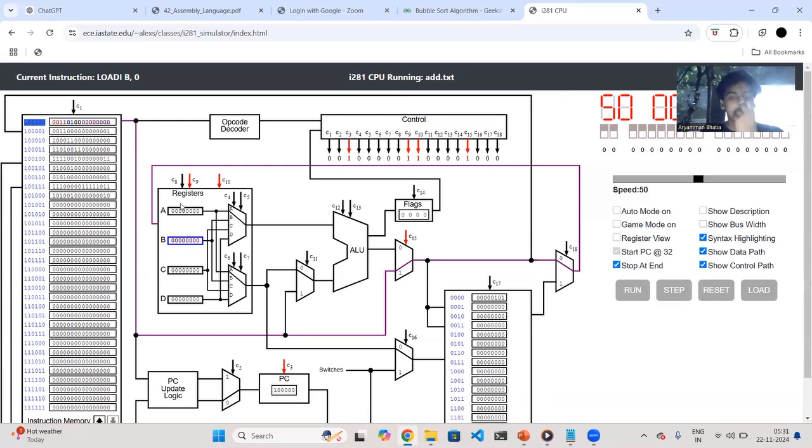Now, how that actually ends up happening is that you have these bottom 8 bits which go through this particular purple path that you can see, and control C15 and C18 are set in such a way that it gets fed back to the register file, and that is the input that is received. We have one enable wire for this register file and two wires to select which register we want to write to, right?